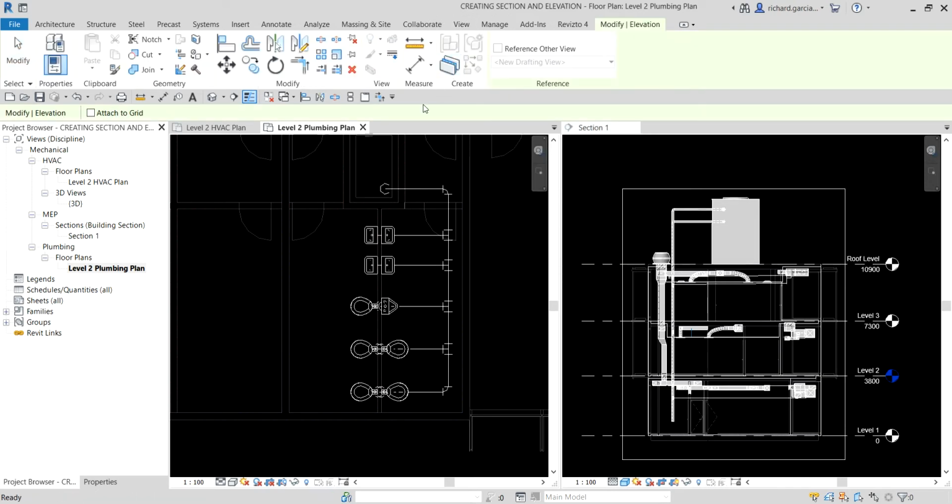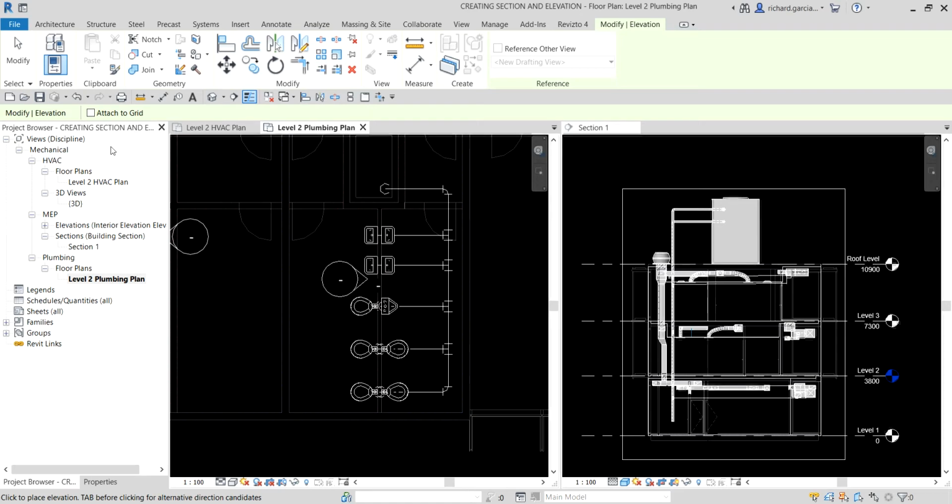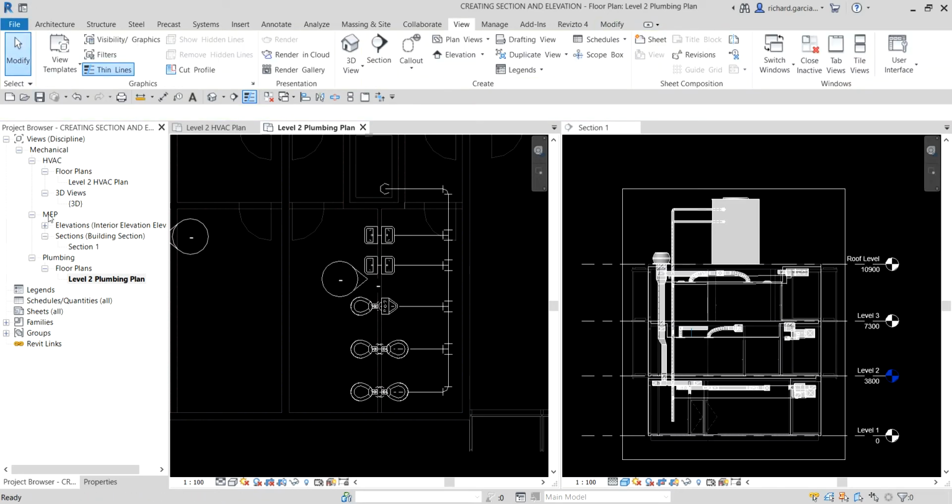You click, and then let's hover our pointer looking to the right side. So automatically it points to the nearest structural element. Okay, so let me just move here and click. There you go. And then I select modify. So as you can see, it's now under the MEP subdiscipline. So I can just adjust that one. So there's my elevation.